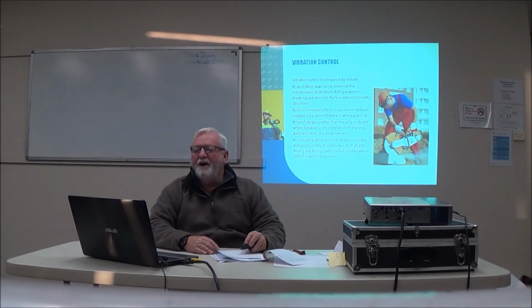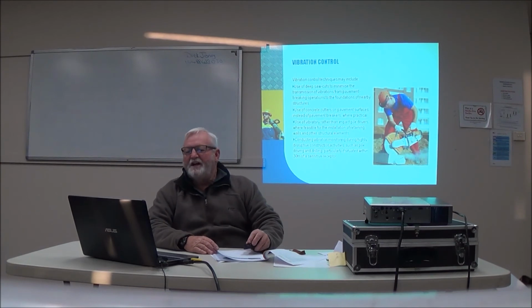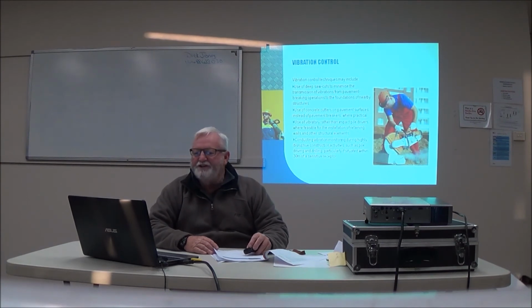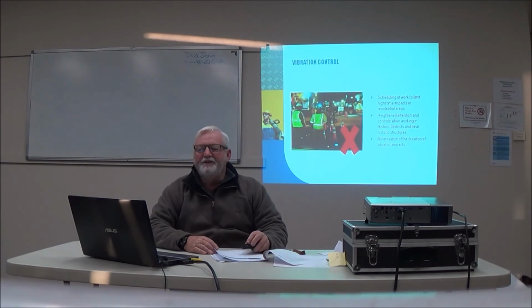Vibration control. Vibration control techniques may include the use of deep saw cuts to minimise the transmission of vibrations from pavement breaking operations to the foundations of nearby structures. Use of concrete cutters on pavement surfaces instead of pavement breakers where practical. Use of vibratory rather than impact pile drivers where feasible for the installation of retaining walls and other structural elements. Conducting vibration monitoring during highly disruptive construction activities such as pile driving and drilling, particularly if situated within 30 metres of a sensitive receptor.